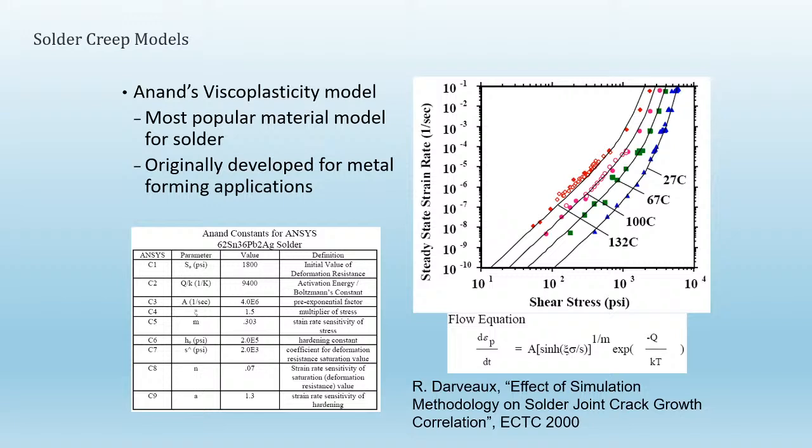Oh, there is a question. Someone asked, how do you decide the height of the solder ball after the solder reflow process? You'd want the geometry. Typically, that's done by measuring the size of the solder ball after the reflow.